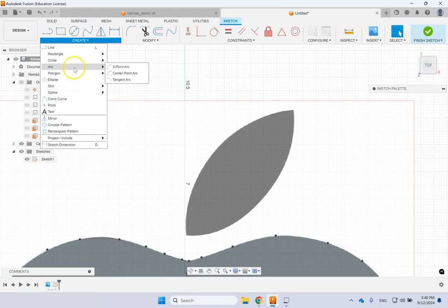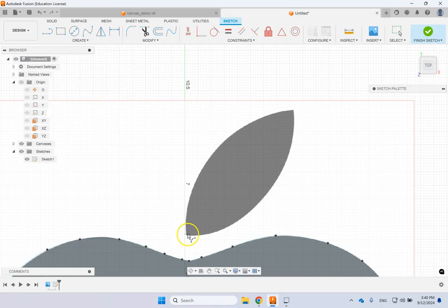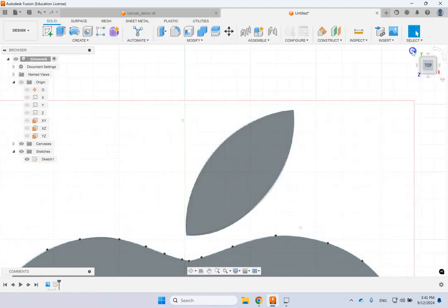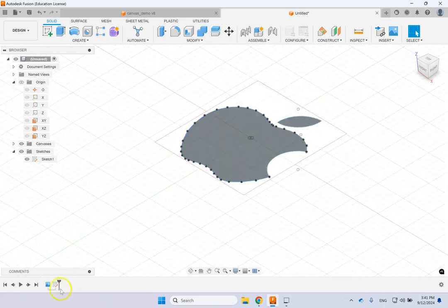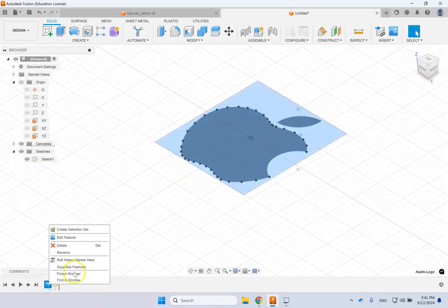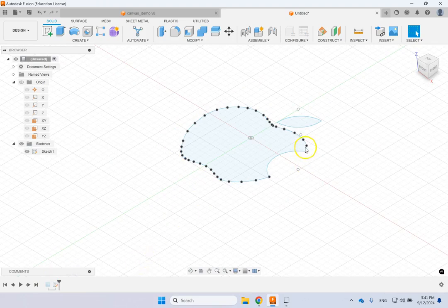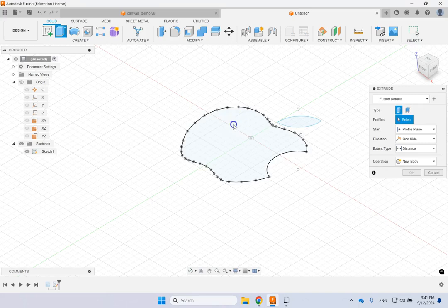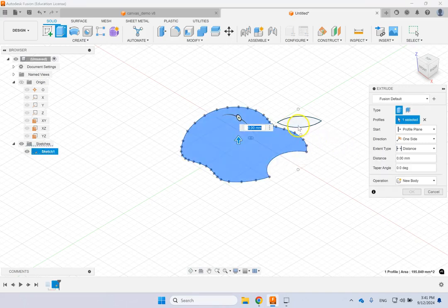And so I personally prefer to, as I said, turn this option off when I'm reversing something with a spline. Okay, so let's say here, and then another one again here, and something like that. You see, this is not a perfect 3-point arc. So once I get my sketch like this, now if you want, you can right click on this canvas and you can suppress it so it's out of the way. So that's your sketch.